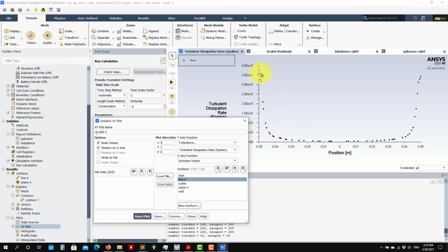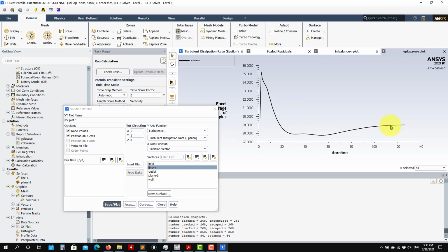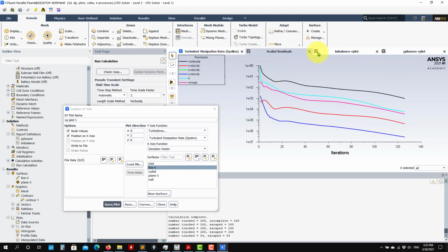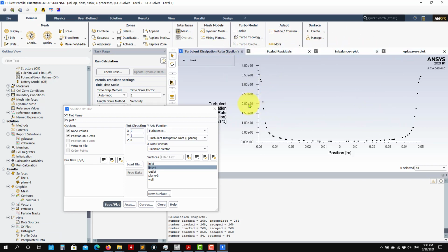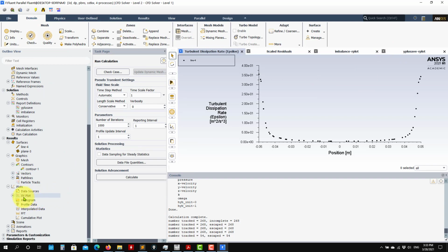So see here that as we're using wall functions, the quantity does not go to 0. It's dissipating everything in the wall. So as you check here, the y plus value, the average is something about 30. So that's why it doesn't go to 0. As you recall the 2D cases, when you have the very, very fine mesh, it went somewhere close to 0 because you're already in the viscous layer, so there you don't dissipate anything. Anyways, and then as you move here, you have these plots.